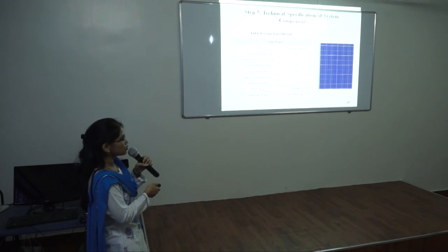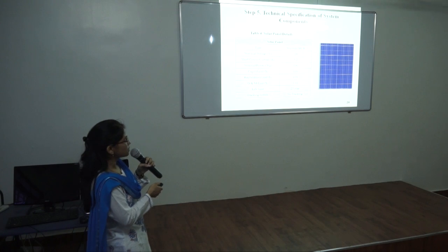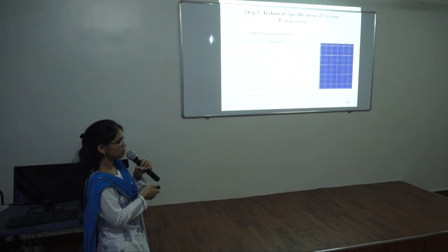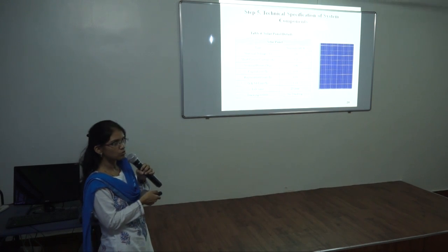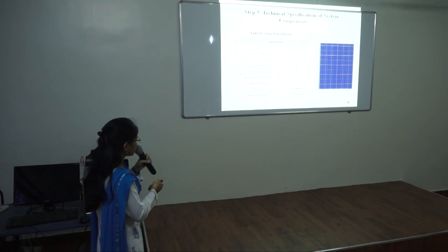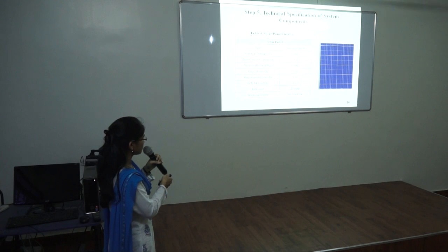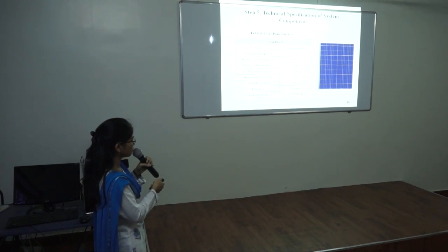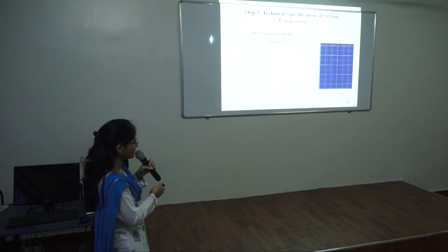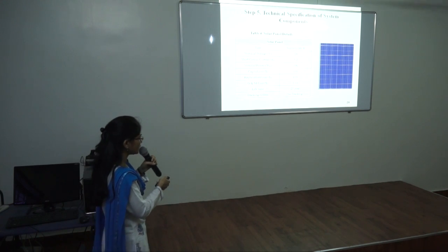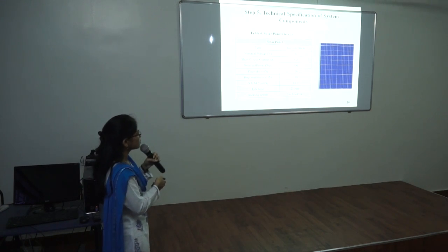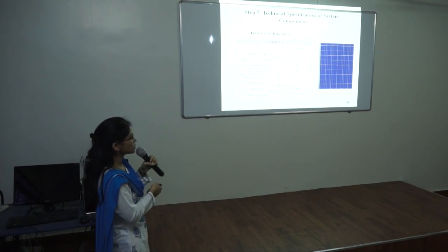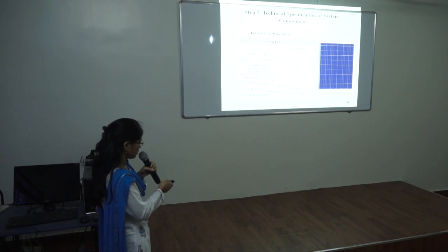After determining the resource input data, the next step is the technical specification of system components. In this study, the selection of system components is based on low cost. The selected panels have a nominal voltage of 24 volts with a short circuit current of 5.9 amperes and a nominal power of 190 watt peak, and the cost is equal to $110. The system is designed with no tracking.